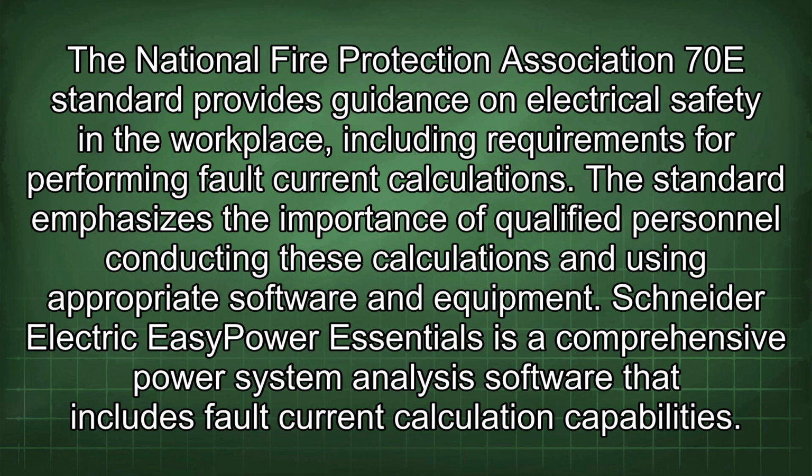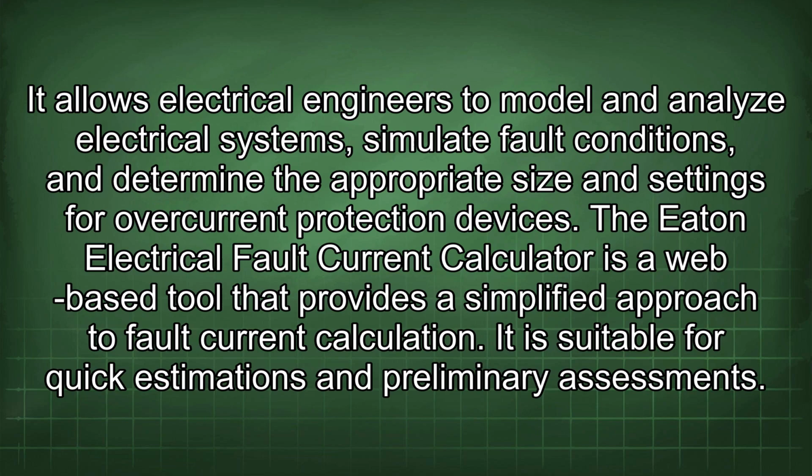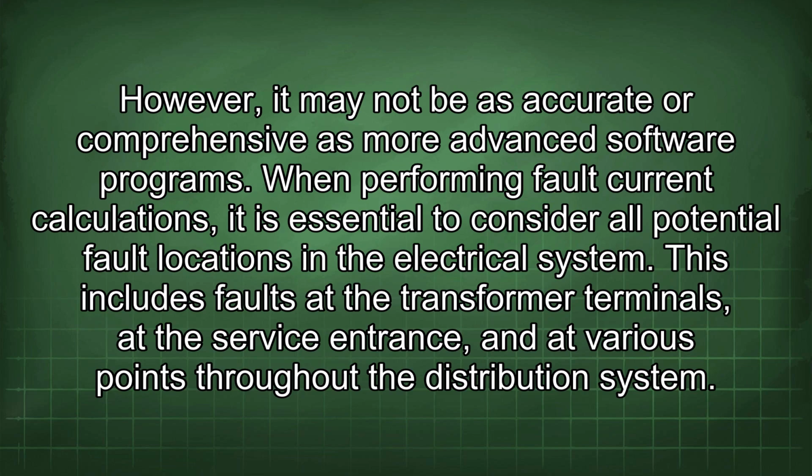Schneider Electric Easy Power Essentials is a comprehensive power system analysis software that includes fault current calculation capabilities. It allows electrical engineers to model and analyze electrical systems, simulate fault conditions, and determine the appropriate size and settings for overcurrent protection devices. The Eaton Electrical Fault Current Calculator is a web-based tool that provides a simplified approach to fault current calculation. It is suitable for quick estimations and preliminary assessments. However, it may not be as accurate or comprehensive as more advanced software programs.